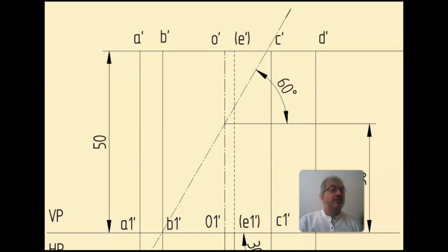Okay. Now we shall see which are all the edges cut by this section plane. Now here we have the pentagonal prism. Now if I look at this edge, AA1 is not cut by the plane. BB1 is cut at some portion over here. You can make out. Then CC1 is not cut. So it's only this portion. This is the line that is cutting the prism. So CC1, DD1 are not cut. So, and this edge at the back EE1 is also cut by the plane.